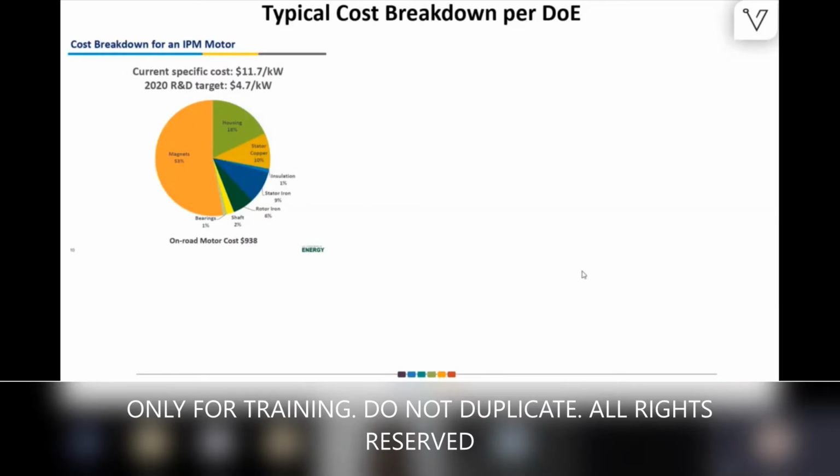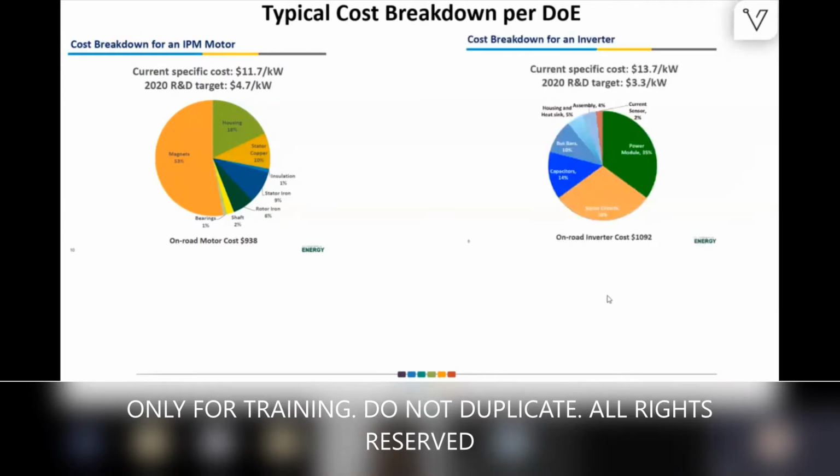So it is similar to our battery. If you put the full vehicle, the battery cost is almost 50-60% of the total powertrain of the vehicle. Then this is how the magnet is equivalent, if you consider just the machine. If you come to the inverter, the power electronics side, the switches and the signaling circuit, your drive circuits, those will be very expensive ones. Next to that are the bulk capacitors, right? Bank, 40%. So those 2-3 elements consume a major portion of the cost.